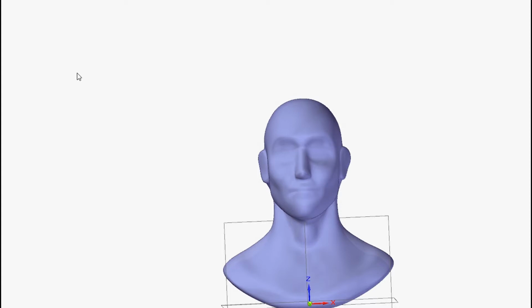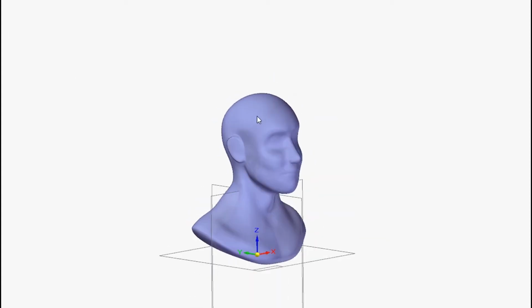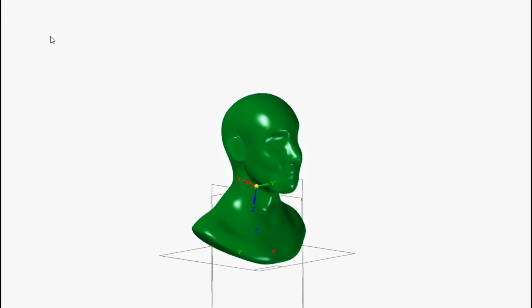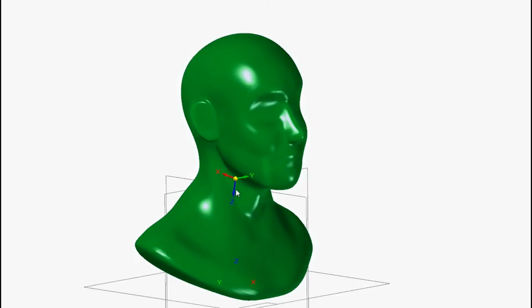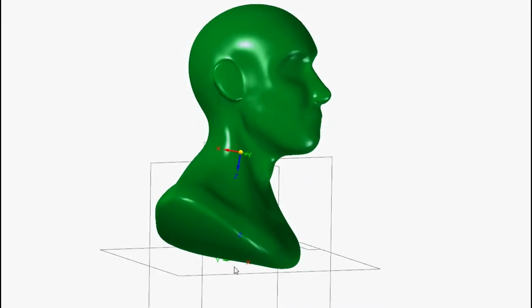This lets you align the mesh bodies to the base coordinate system or a custom coordinate system that you created. So first you'll select your mesh body and accept the selection. Now you have four options. Use principal axes would be to use the coordinate system of the mesh body and align it to that of the base coordinate system.